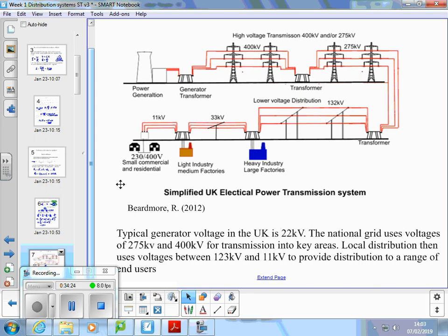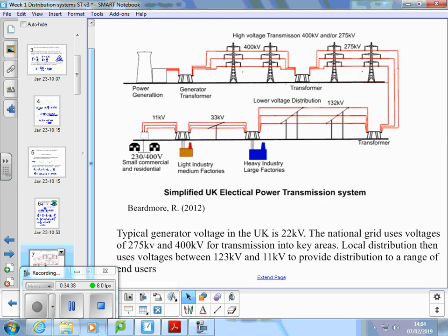Yeah. So those voltages quoted are what's called nominal voltages. So we all know 230 volts at the sockets on the wall. Yeah. So that's the stated voltage, not the peak. When we talk a bit more at some point about the sine wave, that voltage actually peaks at something like 330 volts. And that's something you need to bear in mind if you're working with capacitors, that you need a capacitor that will take at least 330 volts because that's the peak of that waveform.